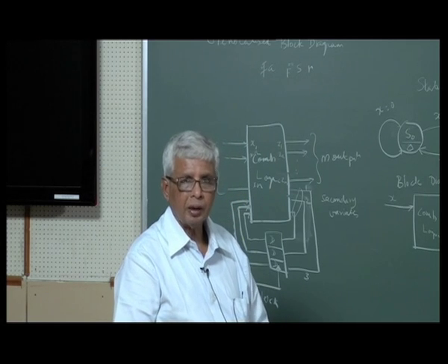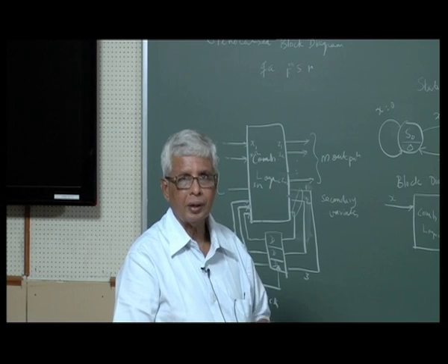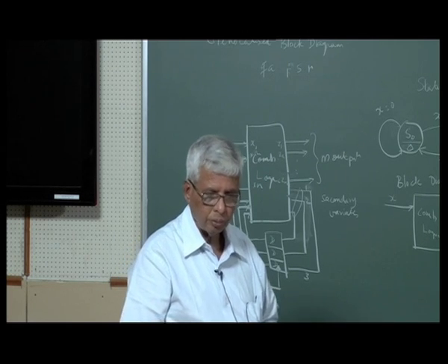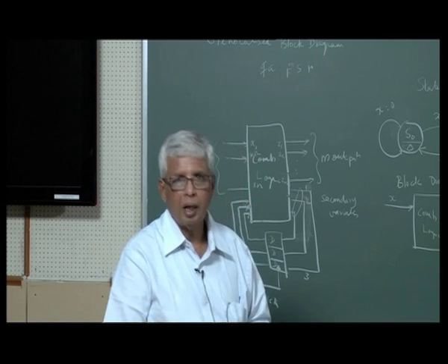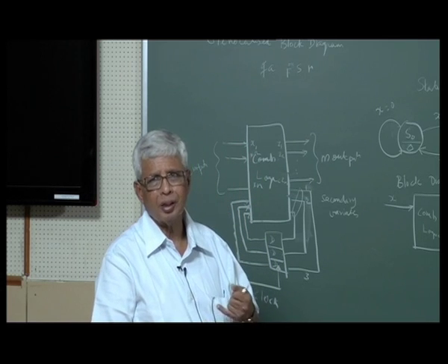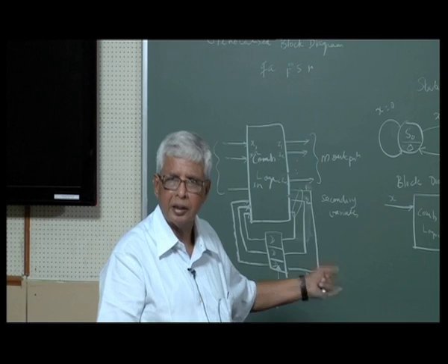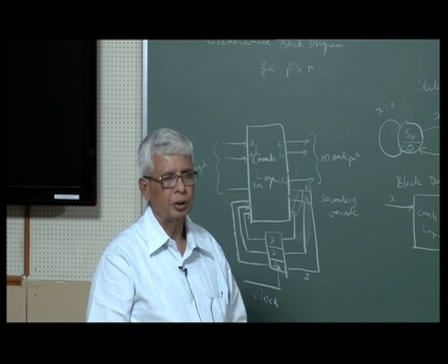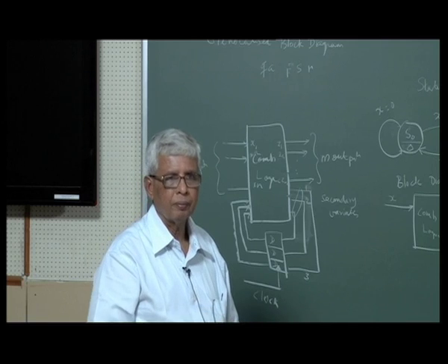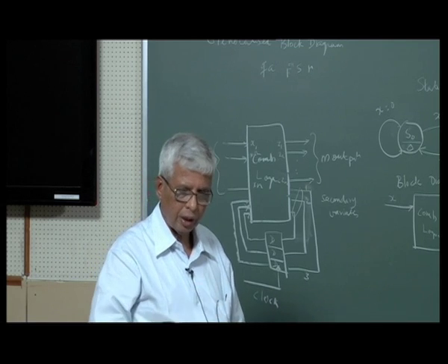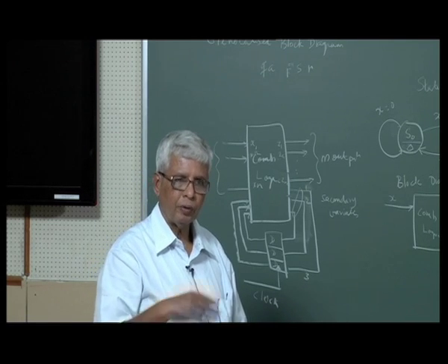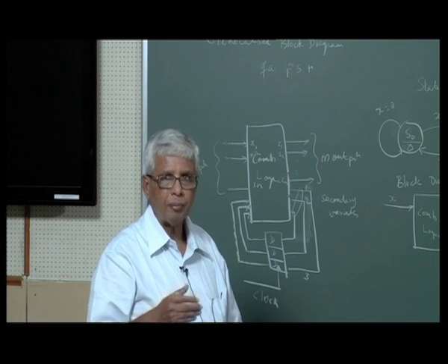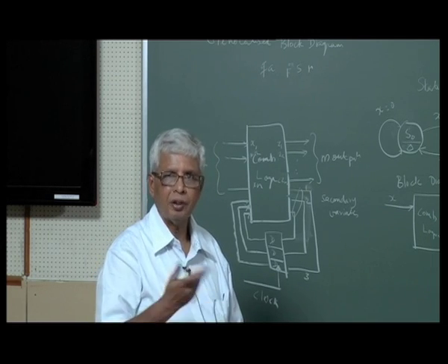and we do the block diagrams, we do excitation tables and we use it to design up counters, down counters. We also talked about ripple counters, which is not used, these are all synchronous counters. Up counter, down counter without any inputs, it goes state to state. Suppose it is a 3-bit, you can go from 0 to 7 and back, or you can stop anywhere and go back to 0, all that we have seen.